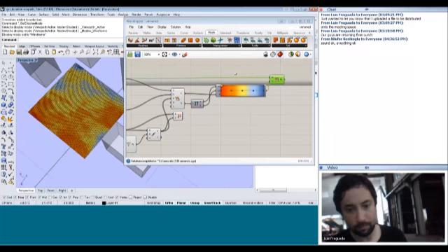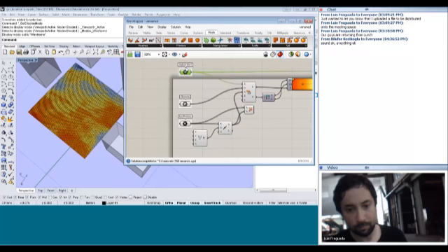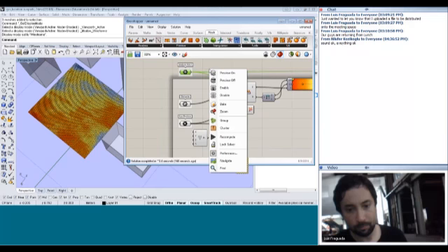What you're probably seeing is the fact that you have your original mesh in Rhino and the new analysis mesh as well. So you should select that and hide it in Rhino. Select the object, type hide, and press enter. Another thing you could do is select the analysis mesh here and turn preview off.